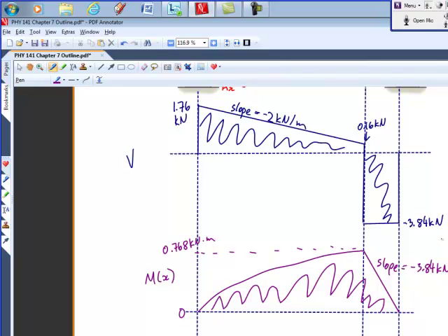Why does the bending moment cause a concave or convex bend in the V? I'm not sure if I understand your question totally. Like if I have a simply supported beam and I put a load in the center, you can see it's going to go concave. Okay. So that means we would have a positive bending moment in our calculations. Yeah. That's what we saw where it went up for the maximum value and then down.